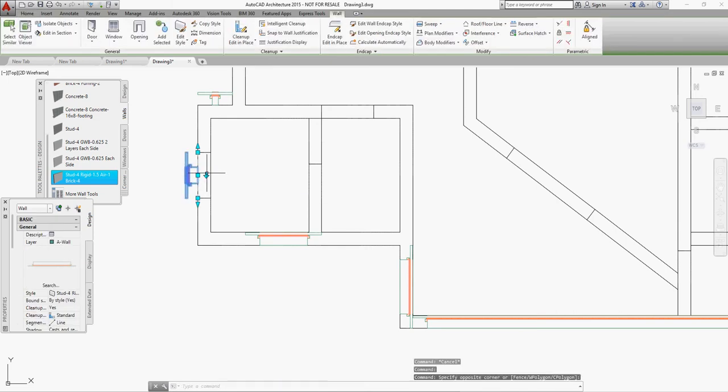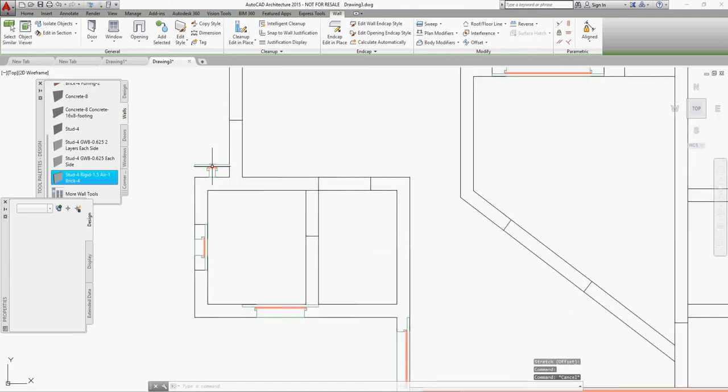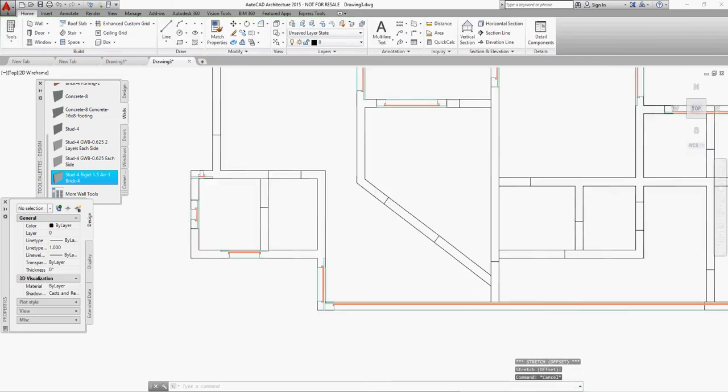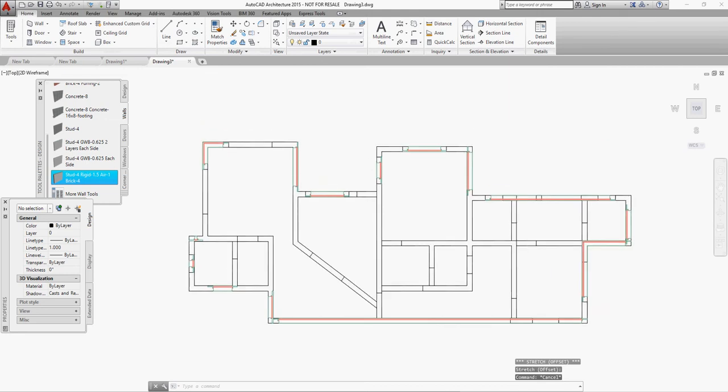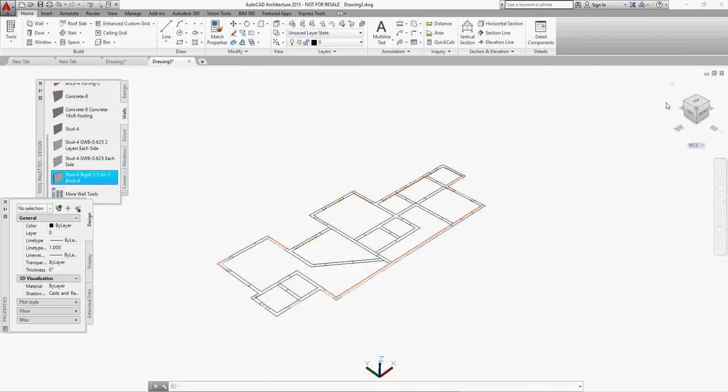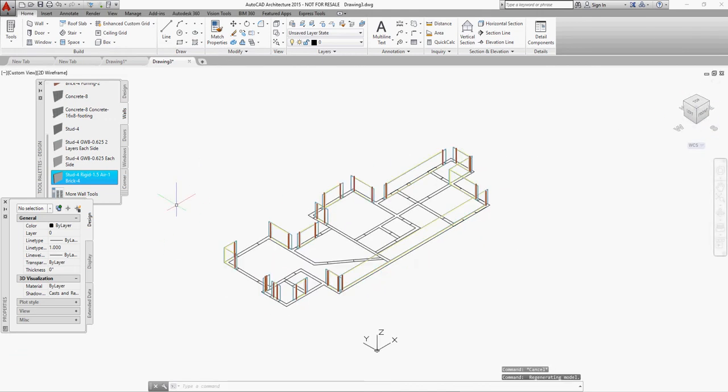And I want to look to see where the baseline is. So right now it's justified baseline. I want that to be justified left. And notice that that shifts the location line, so I can place it correctly.